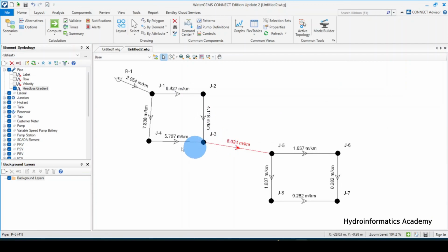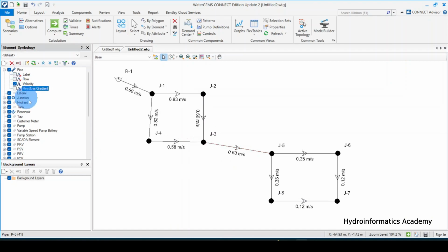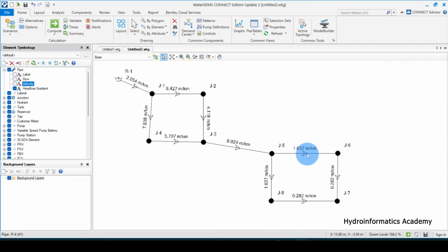And what does that mean? Because the head losses are now reduced. So if I check the flow or the velocity, or water speed, you can see now we're having 0.6, right? At least for now we're having a good result here. So the next option is to deal with this area.